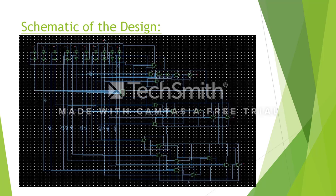This is the schematic diagram of our complete circuit, and here we can see that this part is the input for the input pins. Here we have used buffer circuits to get a smooth and precise active high or active low signal. This part is for output Y3, this part is for output Y2, this part is for output Y1, and this part is for output Y0, and this block is for part A, which I have already discussed.